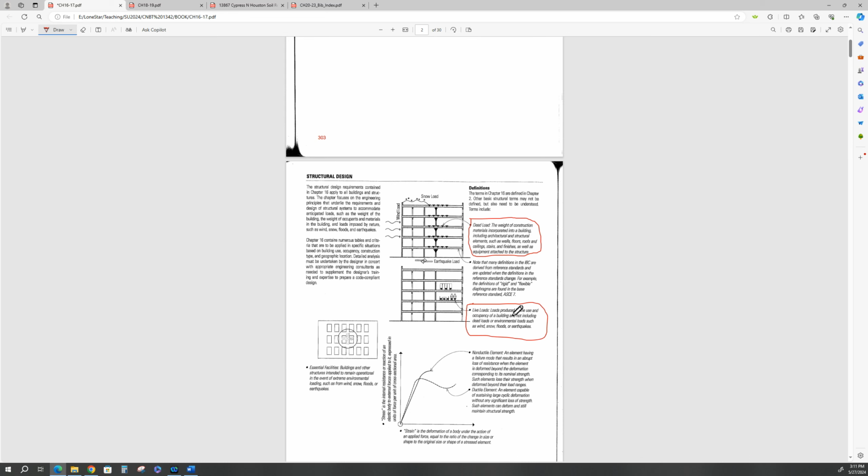So, live loads are loads produced by the use and occupancy of a building, and not including dead loads or the environmental loads such as wind. However, from a structural engineer standpoint, we do treat wind, seismic, rain, and snow as a live load when we do our analysis. But according to Ching and the total intent of the code, he states it's not, but I disagree.